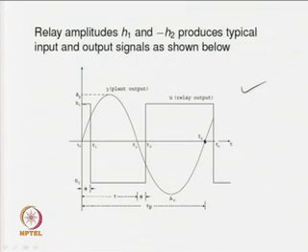So, the switching does not take place at time t equal to T 0, rather the switching takes place at time t equal to theta. Similarly, the switching is getting shifted by theta seconds, so that the switchings at time T 0, T 2 and T 4 take place after time theta.